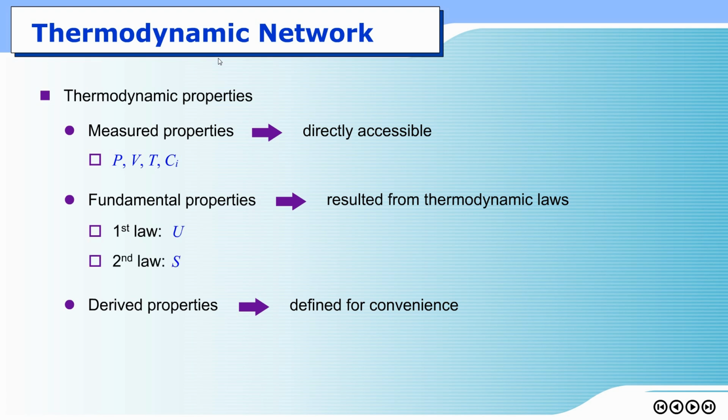Right? Then in lecture 4, we introduced the parameter called entropy. The parameter itself was derived based on Carnot cycles to get dS equal to δQ over T, but the heat itself must be reversible heat. I also mentioned that according to statistical thermodynamics, entropy can be thought of as an indicator for chaotic dispersion of mass and energy within the system.